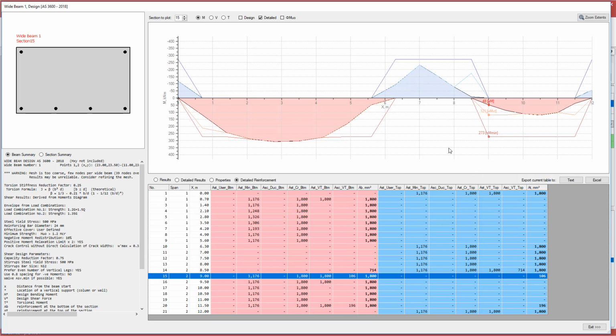However, this longitudinal force due to shear and torsion is causing a net tensile force in the compressive zone. Initially we had no steel up there, but to satisfy the equations of section 8 we had to put something small in the compressive zone. So why we see the number here: this was a calculation of the bottom of the section. It produced compressive steel, which is in the top, so this 106 is passed through to the top of the section. So that's where that number comes from.